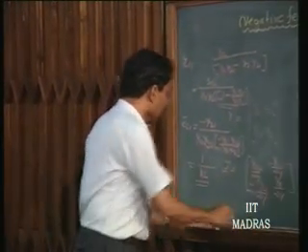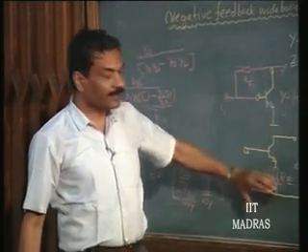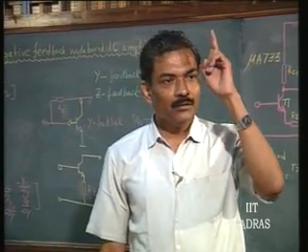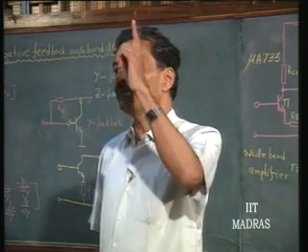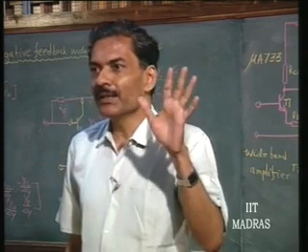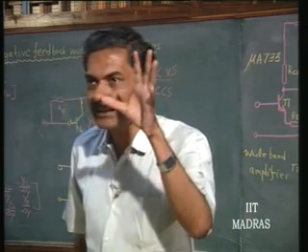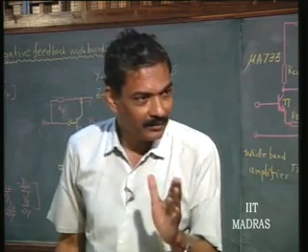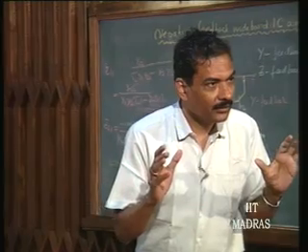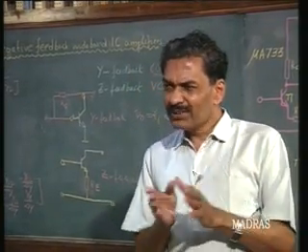Now, these are basic things in negative feedback that we should be aware of. The reason we have used a single stage is because it is only in the single stage that we do not have more than 2 time constants, and a single stage feedback amplifier never becomes unstable. It does not need any frequency compensation. Whatever the negative feedback, it is never going to become unstable because it is at most a second order system. A system is likely to become unstable when it is third order or higher, and that also when the loop gain is higher. So, in wideband amplifiers we always select a single stage, not multiple stages. Multiple stages will result in serious problems. We will come to that. We will still go to multiple stages later.